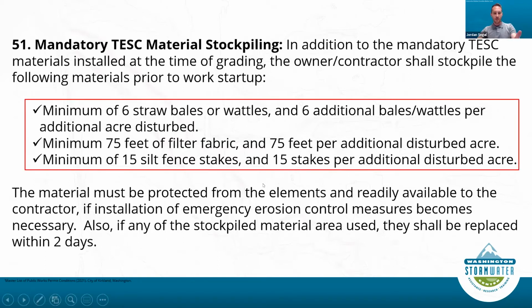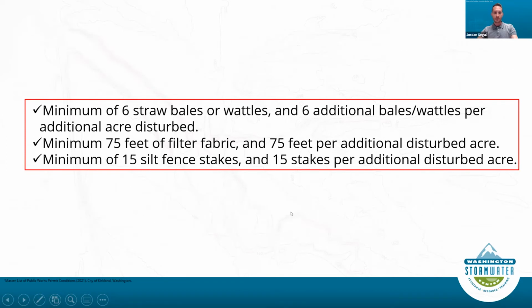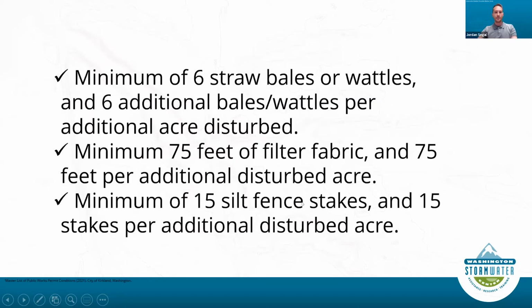And in this, I'm looking right at the middle. I see BMPs. I'm seeing an amount that the city needs to consider. And so maybe that's an idea of, maybe my site needs a laydown area. Maybe my site needs to consider, of course, silt fence, but maybe it needs straw bales and straw wattles as well. This is what this city is requiring. How am I going to accommodate that for the contractor on the site?